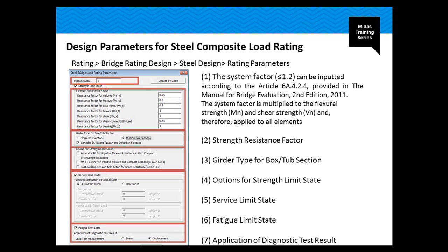Then we have the service limit state. In this case, you can limit the stresses in the structural steel, or you can manually input the design load and the legal load or permit load stresses, limit stresses, whether it's compressive stress or the tensile stress.